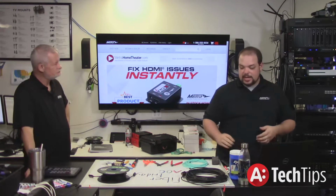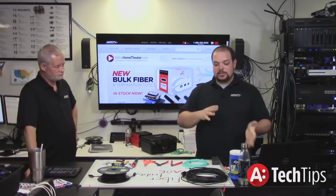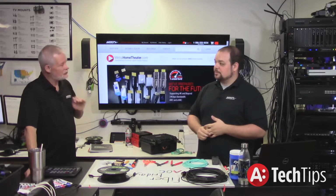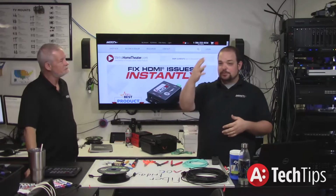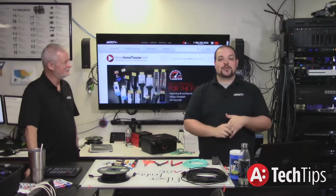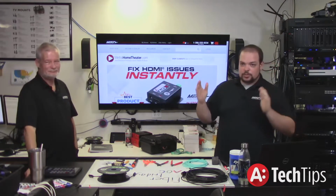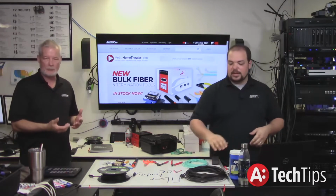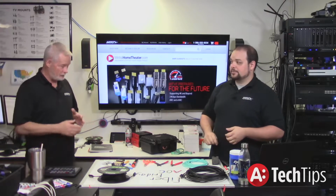So what we're talking about today, like we said before, is Fiber Friday. We're talking about the AOC and HDMI AOC and what the biggest differences are. I have some questions right out of the gate. Is our fiber 24 gigabits capable right now? Yes. And why is that? Because we are using 4 channels at 6 gigs per channel. So right now we are able to do 24 gigs on our HDMI AOC cable. Which means when 2.1 starts to roll out, we are prepped for the beginning stages of HDMI 2.1 right now, as a transmission method.